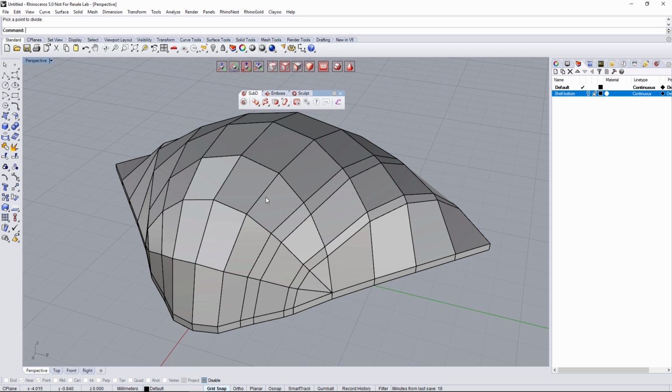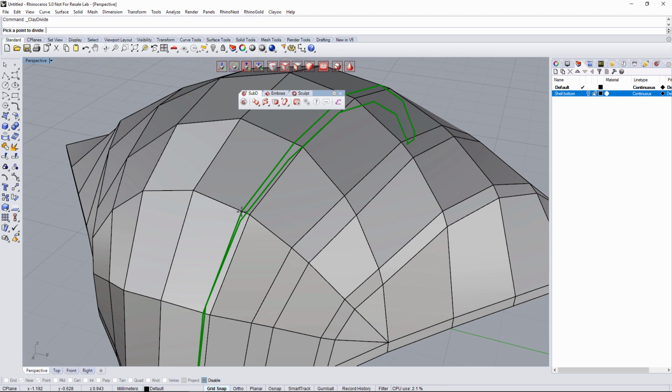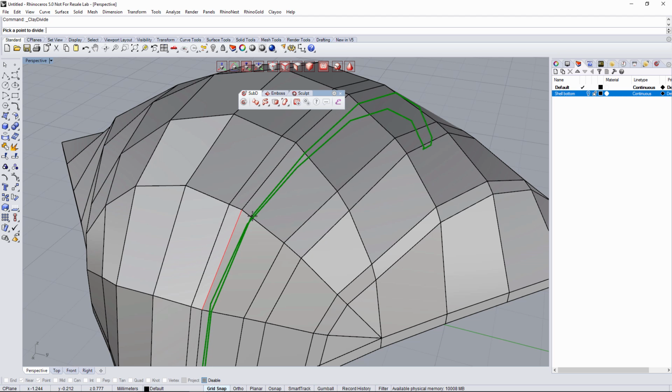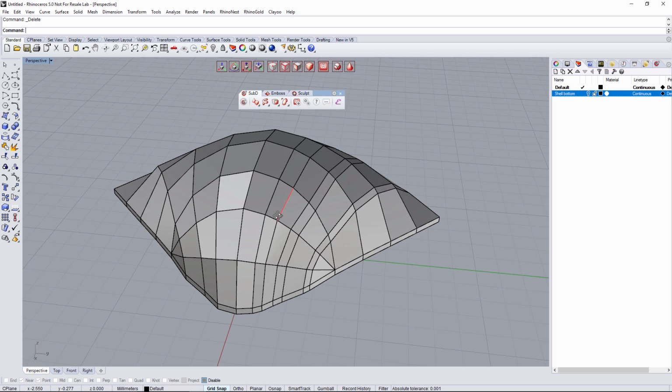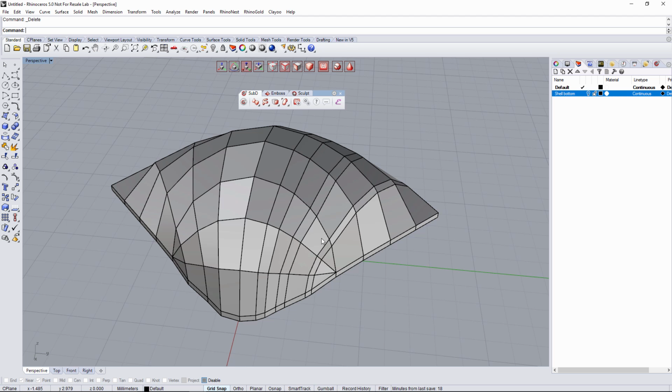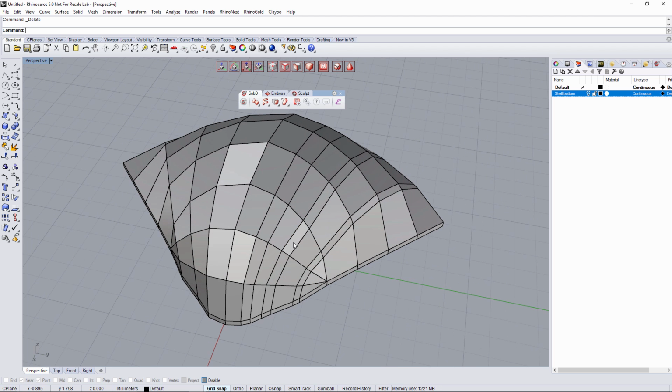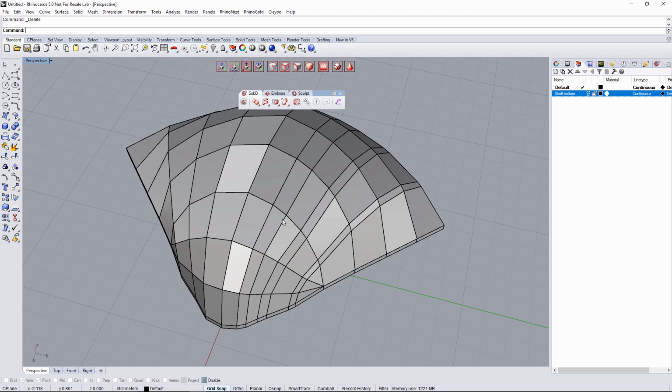In the next loop of edges, I'm gonna use the tool divide. So I'm gonna go to the edition tab and divide. Okay, and it's gonna allow me to display this amazing red line. So I can click, for instance, if I want the existing loop of edges to be the central one, so I can create one on one side. So for instance here, right click to repeat the command and create the other one, for instance here. Okay, and now I can double click on the central one and delete it. Okay, in here we have seen three different ways: split sides and deleting the central, split sides and automatically deleting the central, and with divide.